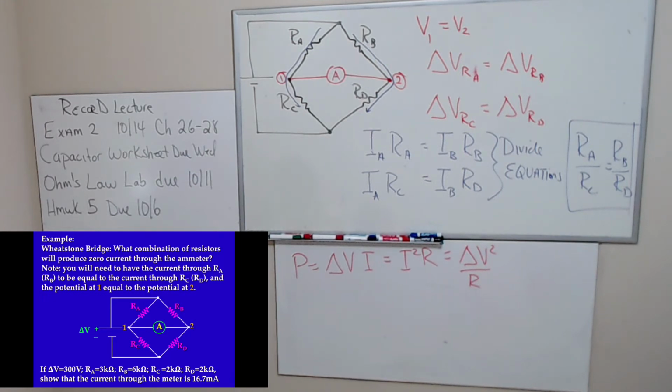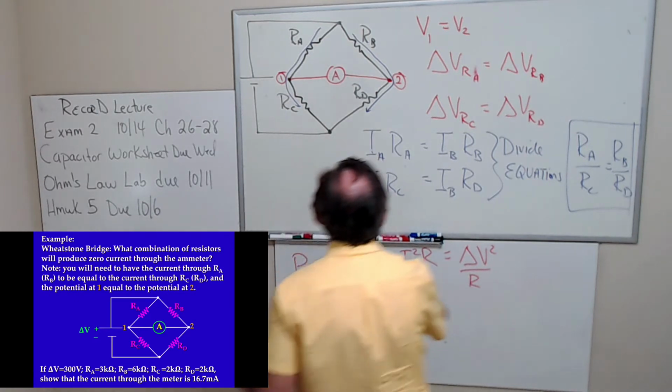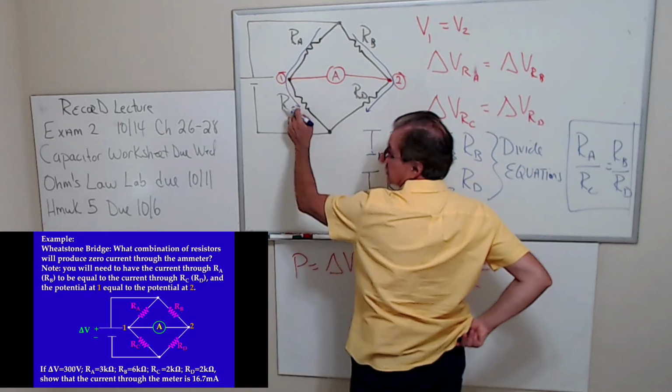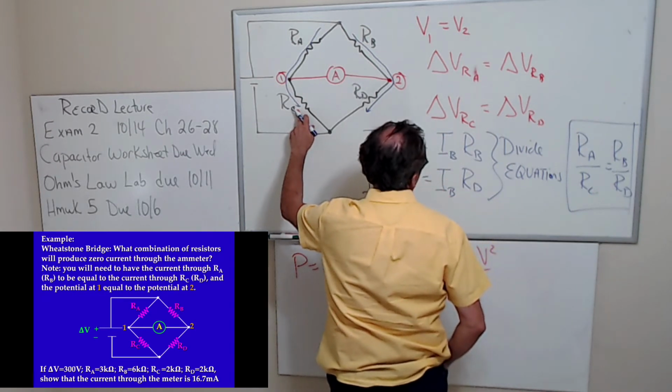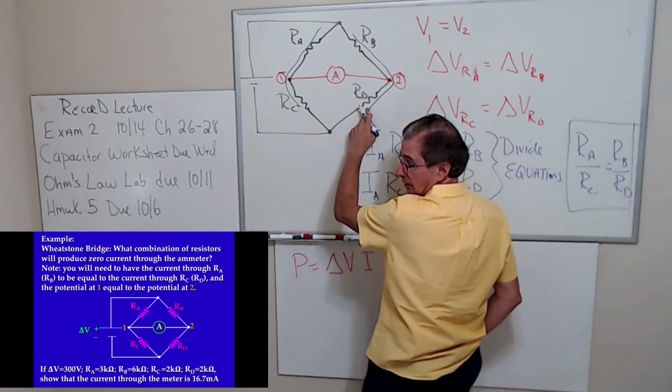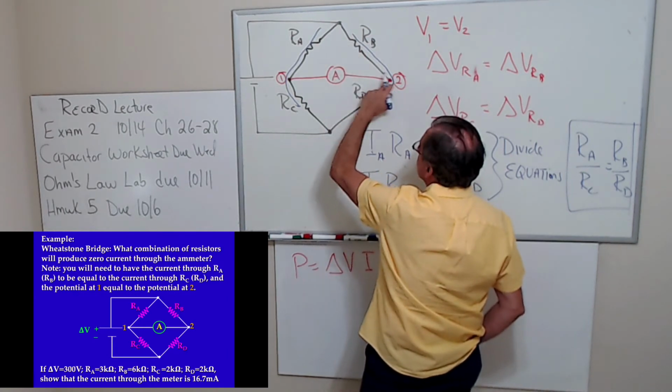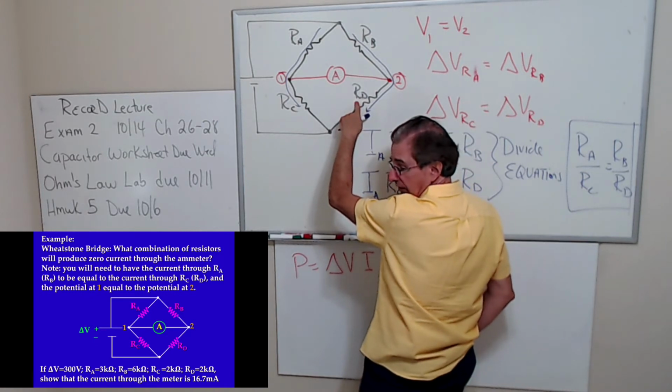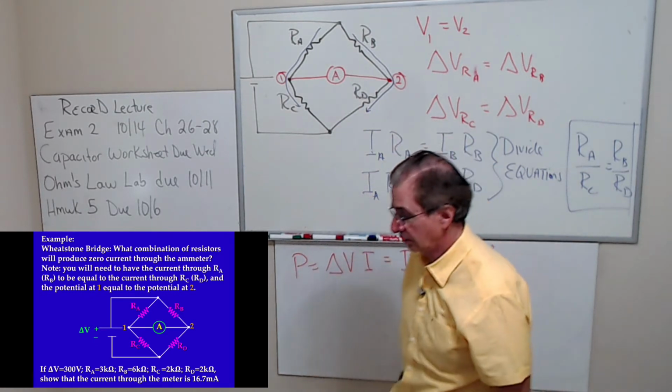Yeah, we can do that, Patrick, too, I guess. Well, if we put a wire, then there's no way to sense there's no current, right? What people would do using this technique is put two known resistors here, and a resistor you can change here and an unknown here. By varying this resistance until you get no current through here, you can determine this value. And that's what this circuit was used for.